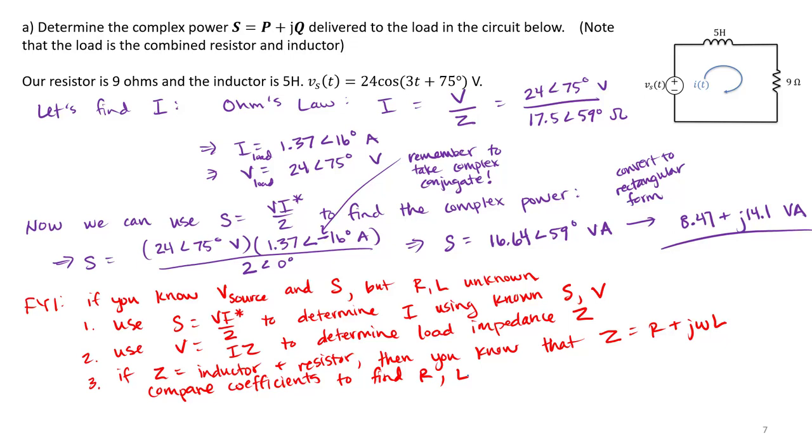So you might also see problems on the homework or in our textbook where you know the complex power, but you don't know the identity of the load. And as you can see, you can basically approach this problem in reverse in order to determine the unknown load.